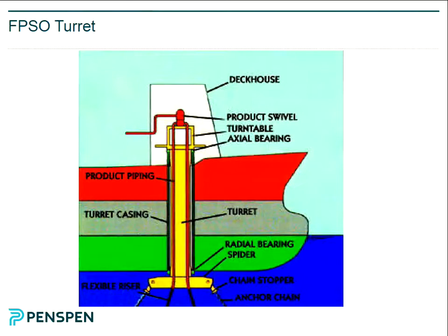Where subsea production does come into its own is if you had a big platform which is full to capacity, it could take oil, but it can't do any more processing because it doesn't have the capacity for water or gas. So you can produce oil to it, but it can't clean up your oil because there's not enough space on topsides to add the extra equipment. That's where subsea processing might come into its own, because you can process it here and then just send the oil to the platform.